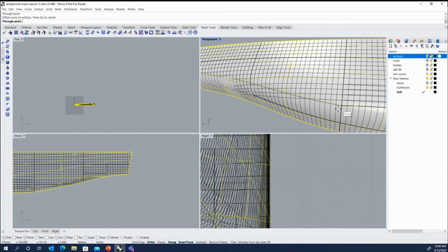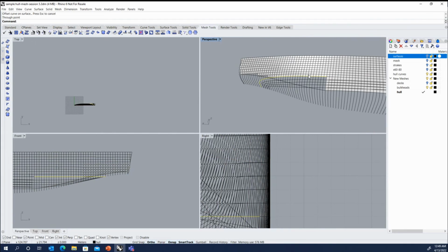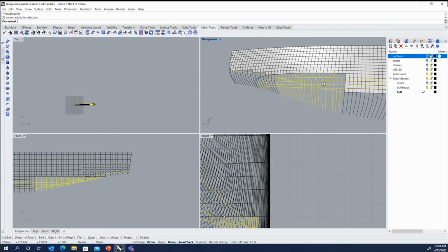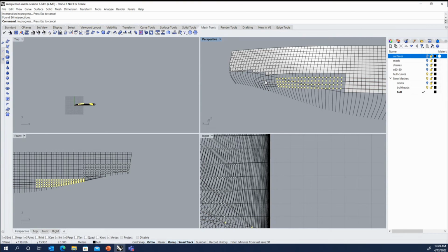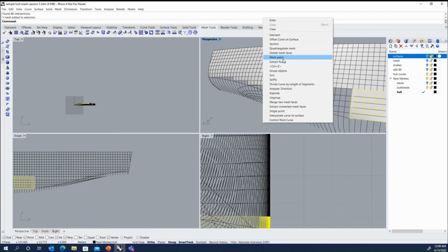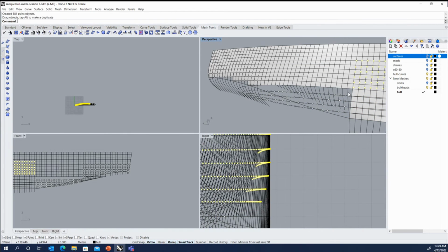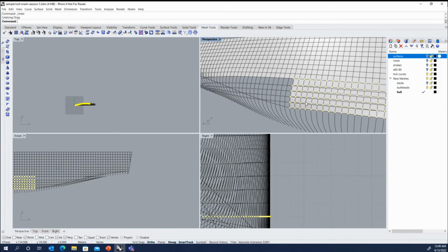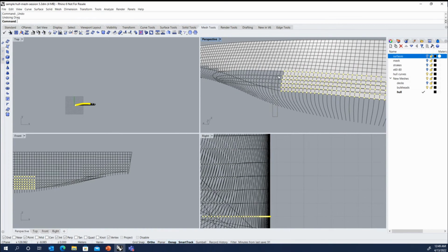And we don't need that one, it's below the curve already. And again, we don't have to do two sets because we want all the intersections between these. It grabbed a geometry point when I went to create the window, so it moved all my points. So I'll hit Control Z to undo that. Now it still kept the selection set, so I'll start it way out here so I can unselect all of those. Hit delete.